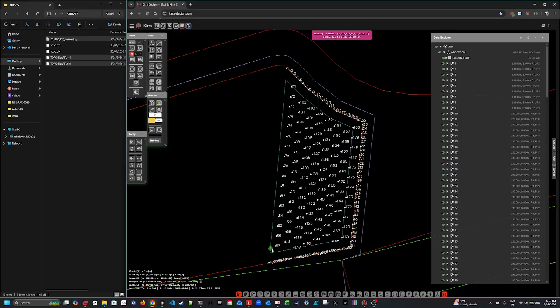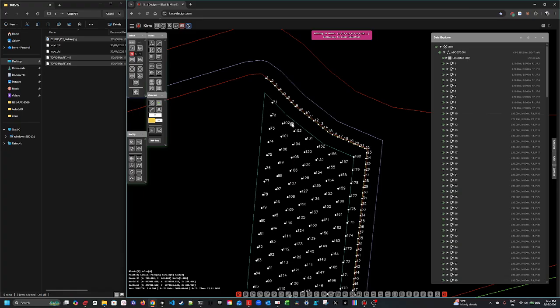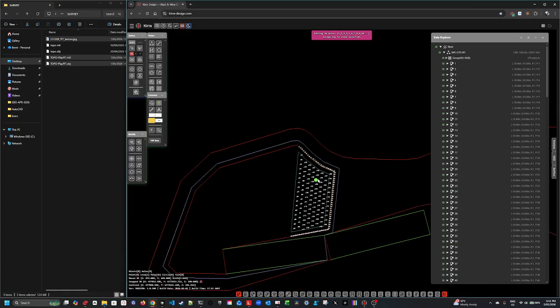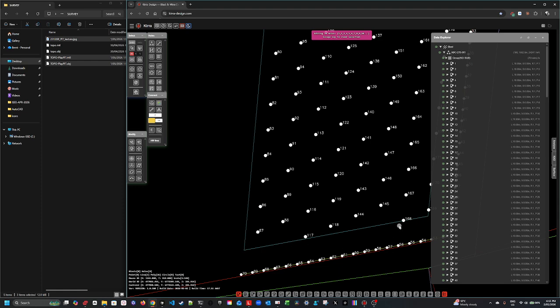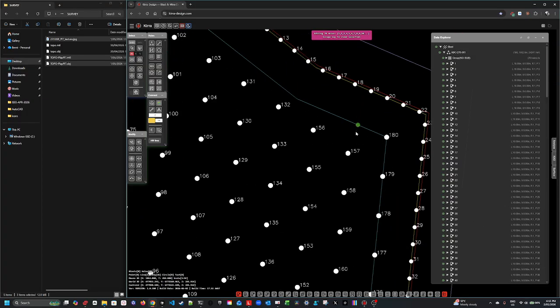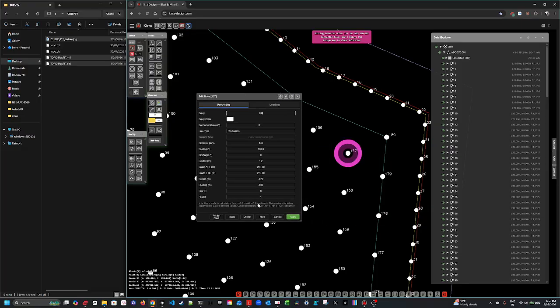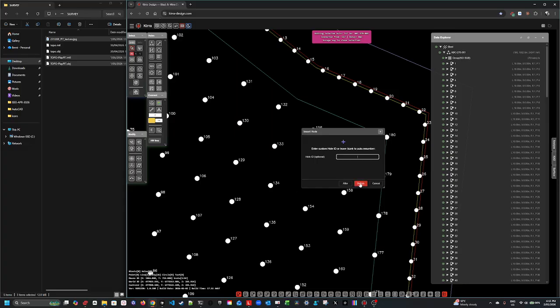We've got a few gaps, obviously, but we can add holes in here. So we're going to insert some holes at the end of the row, and insert holes at the end of this row. Let's do that over here. We will select our select tool, select our hole, right click, and the key here is, this is an insert before.